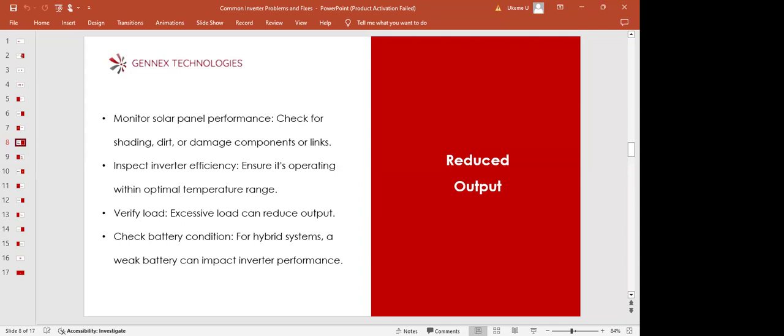If your load is so heavy that it pushes the battery to low and shuts down, when the load is off it, the inverter will see that the voltage is up, so it will come up again. But if the battery is bad, sulfated, it will be doing the same thing. So you need to test the battery properly and be sure what the condition of the battery is.